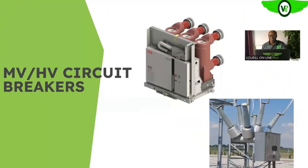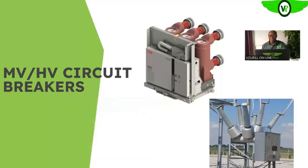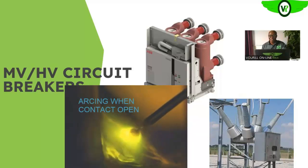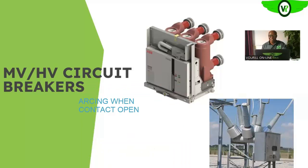But before we appreciate how these circuit breakers that operate in the medium and high voltage environment operate, we need to appreciate the mode of arc formation when a circuit is broken. Remember, earlier we said the function of the circuit breaker is to quench the arc, or rather to make or break the circuit while on load. When the circuit is made or broken while on load, an arc is bound to form. The strength of that arc is dependent on the magnitude of current flowing through the circuit, and also on the magnitude of the voltage.